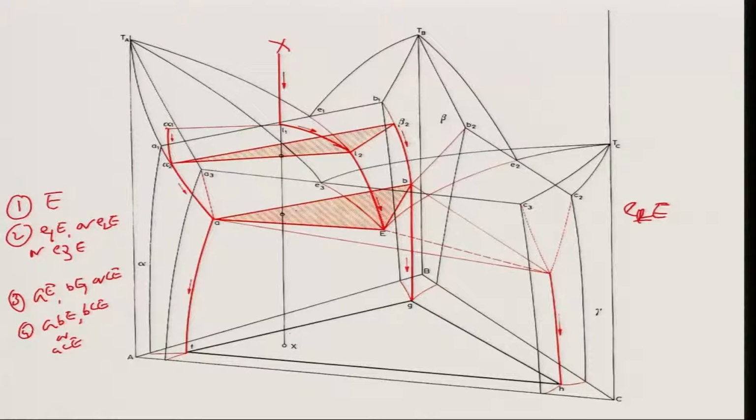This is the thing, let me write down again, it is sitting on that. Because it is sitting on this, it has to crystallize both alpha and beta, because this is the eutectic, u1, a eutectic corresponding to the binary of AB producing alpha plus beta. Therefore, the valley connecting u1 to E will lead to crystallization of both alpha and beta,